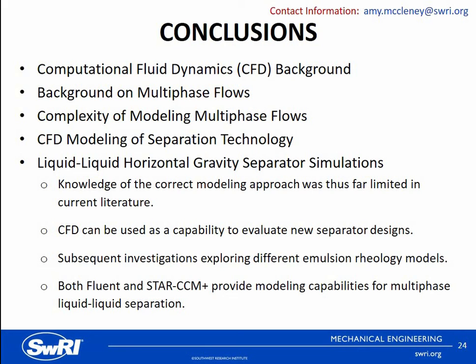Subsequent investigations looked at exploring different emulsion rheology models. And finally, we believe that both Fluent and STAR-CCM+ provided modeling capabilities for multiphase liquid-liquid separation, so both perform very well, within plus or minus 10% of our experimental data.